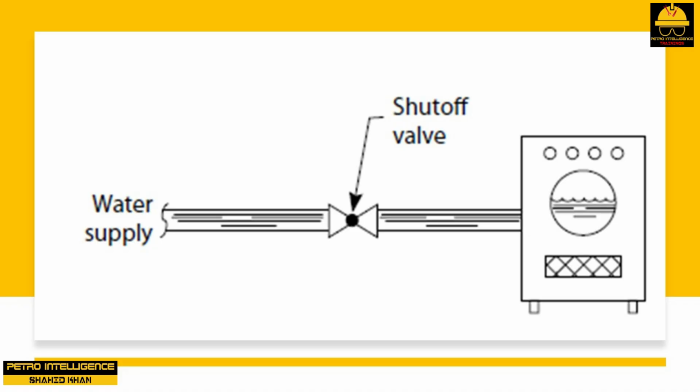This is a picture of our washing machine as it was originally installed. Whenever the shutoff valve on the water supply line closed, water hammer, or hydraulic shock, would shake the water piping. The momentum of the water flowing in the piping would be suddenly converted to pressure. If the end of a piping system is open, as into a sump, then the momentum of the water is converted to feet of head. But if the end of the piping system is closed, then the momentum of the water is converted to pressure.